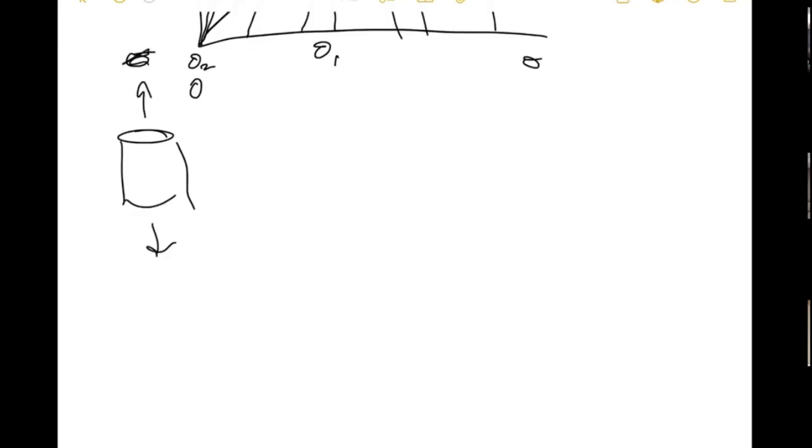So direct tension test. Help me again. You measure ET and you measure tensile strength. You take this, you put it in a triaxial cell, and usually if you have a triaxial cell, they're quite expensive. You could put this in confining fluid and just put super small confinement on it, and you could say that's like a UCS test. Or you just do a UCS test, which is easier. You can see the specimen just sits there.